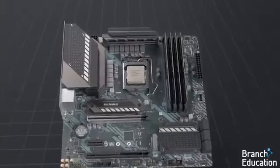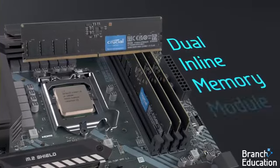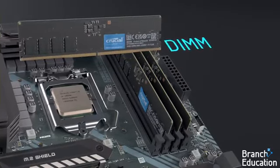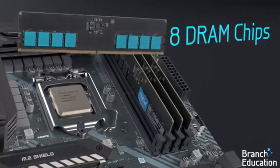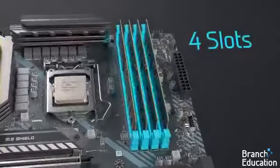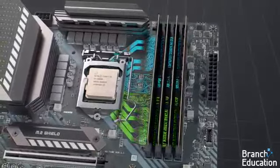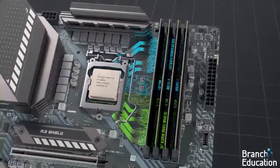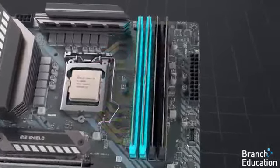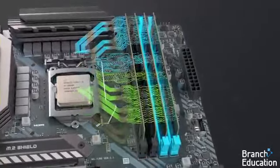To start, a stick of DRAM is also called a dual inline memory module, or DIMM, and there are 8 DRAM chips on this particular DIMM. On the motherboard, there are 4 DRAM slots, and when plugged in, the DRAM is directly connected to the CPU via 2 memory channels that run through the motherboard. Note that the left 2 DRAM slots share these memory channels, and the right 2 share a separate channel.